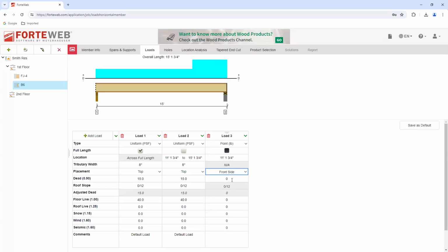And now I'm going to add my dead load, and I'm just going to cheat and use what's in the manual, 36 and 120 for the live. So now you can see that it has that point load coming across on this beam. And once again, I should have been adding these, each one given a default of normal loading with 8 inches of trib, another 8 inches of trib added at the flush beam, and then the point load from the flush beam. I could have put that information in there.